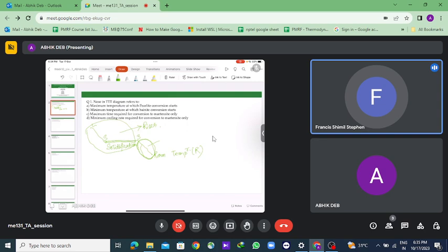In that case, they might consider that it has already taken the shape of a semi-solid, and the shrinkage allowance takes care of the entire thing. But I think from the solidus temperature line to room temperature is what is taken care of by the shrinkage allowance.